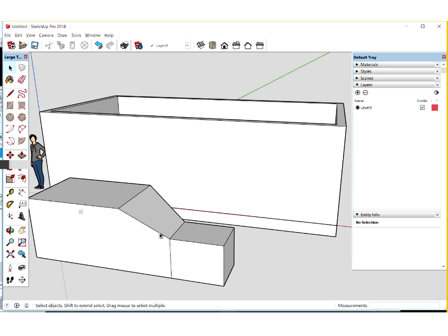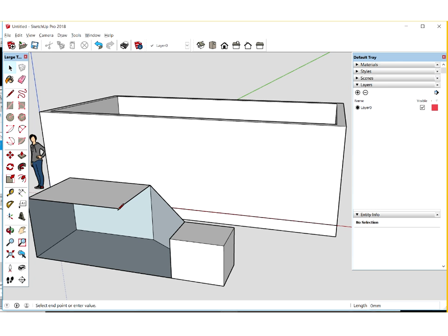Also remember that all SketchUp geometry is hollow geometry. I just deleted that edge there. We can see inside that double box shape there. Don't panic if you ever accidentally delete an edge. Figure out which one it is. All faces, all surfaces depend on a group of coplanar edges to form that surface. So we can heal that by just redrawing in the edge which we accidentally deleted.